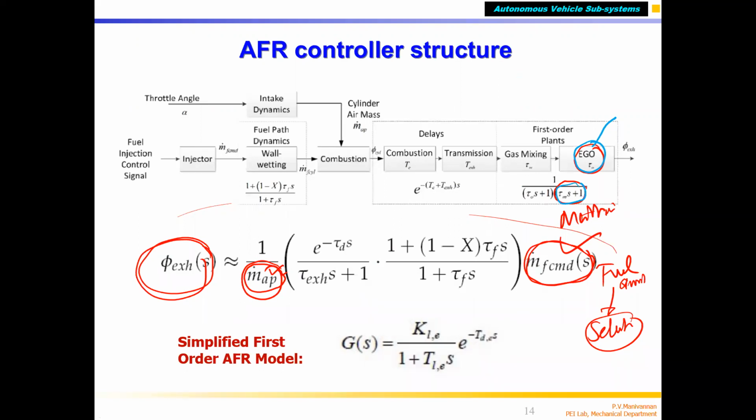Okay, understood, sir. Open loop is also there, sir? Open loop is the lookup table only. If you remove this EGO sensor, it becomes open loop. If you remove the EGO sensor dynamics in the mathematical equation, then it is open loop. In that case, only the throttle position will decide the air-fuel ratio: throttle position, wall dynamics, the fuel dynamics, the fuel puddle evaporation. Only the throttle dynamics will decide. Okay, right. We stop here. We will see tomorrow, 8 o'clock.